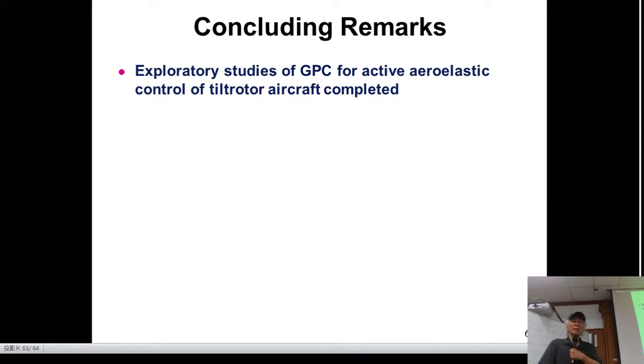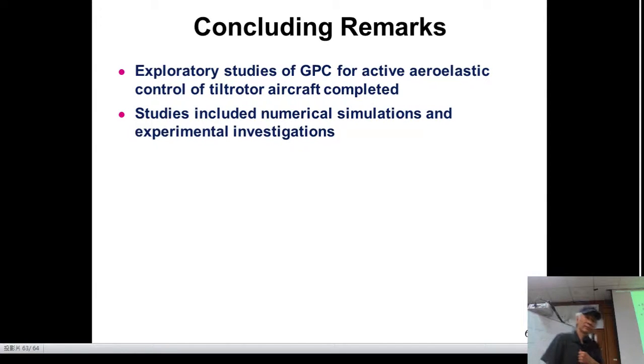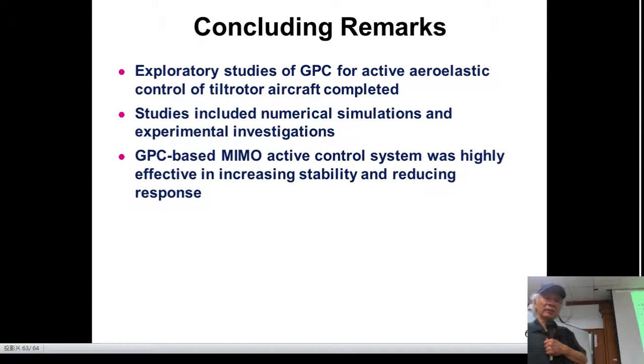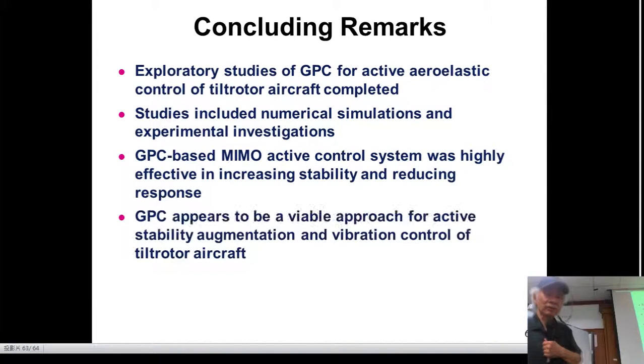So the GPC exploratory studies of GPC for active aeroelastic control of tail rotor aircraft completed in this, and it had very good, successful results. And we include the numerical simulations, like experimental investigations, multiple input, multiple output. GPC was highly effective in increasing stability and reducing the responses.